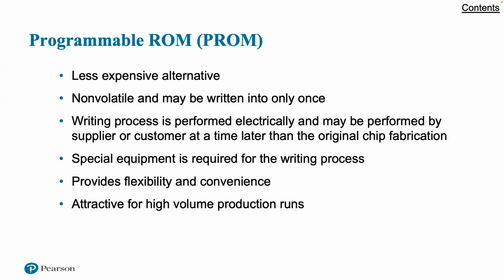Another alternative is something called a programmable read-only memory, or PROM. When a small number of ROMs with a particular memory content is needed, a less expensive alternative is the programmable ROM, or PROM. Like the ROM, the PROM is non-volatile and may be written into only once.